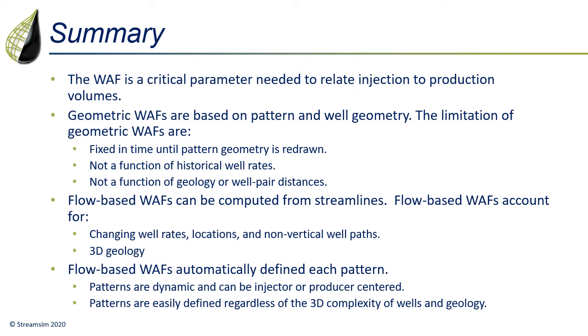Flow-based WAFs can be computed from streamlines. They account for changing well rates, locations, and non-vertical well paths, as well as 3D geology. Flow-based WAFs automatically define each pattern, meaning that patterns are dynamic and can be injector or producer centered. In other words, regardless of the complexity of the flood, patterns can always be defined in a robust manner using streamlines.